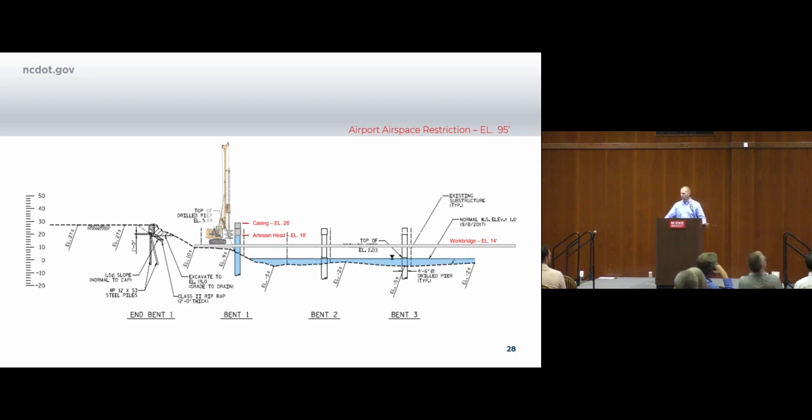So we got Geotech or a consultant to come out and put a piezometer in to check what the artesian head pressure was, and it turned out to be elevation 18, which was 4 feet above the work bridge, right? So you can see where the water in the river was, and then what that head pressure was from the artesian conditions. And so you think, okay, well, 4 feet above where the work bridge is not too bad, right? But to maintain a positive slurry level above it to offset the pressure of the artesian, generally we like to be at least 5 feet above that.